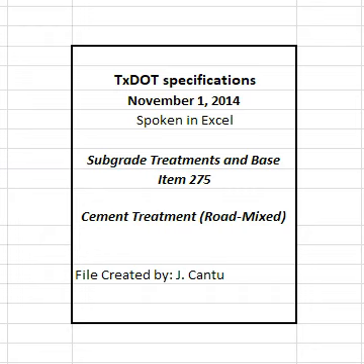4.4 Mixing. Thoroughly mix the material and cement using approved equipment. Mix until a homogeneous mixture is obtained. Sprinkle the treated materials during the mixing operation, as directed, to maintain optimum mixing moisture. Spread and shape the completed mixture in a uniform layer.